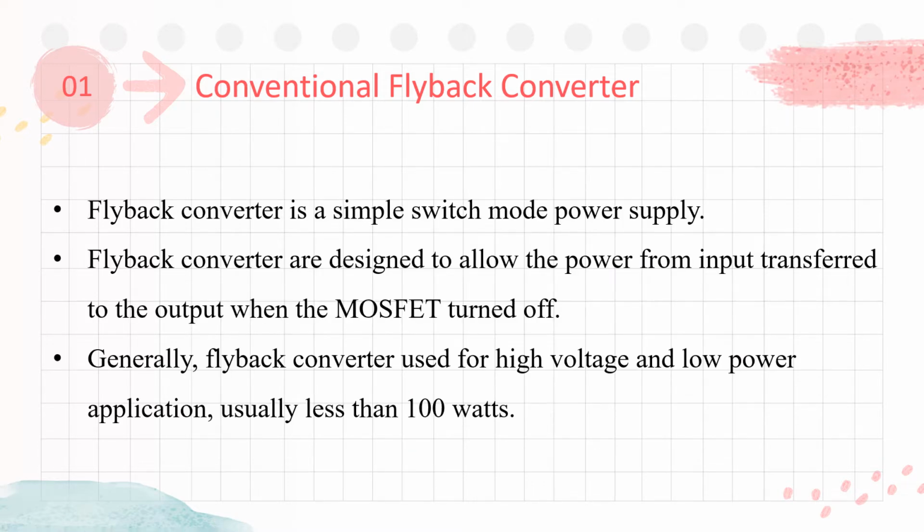Flyback converter is a simple switch mode power supply. Flyback converters are designed to allow the power from the input transferred to the output when the MOSFET turned off. Generally, flyback converters are used for high voltage and low power application that usually less than 100 watt.